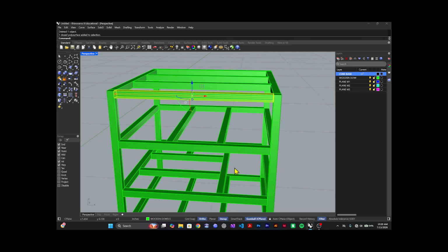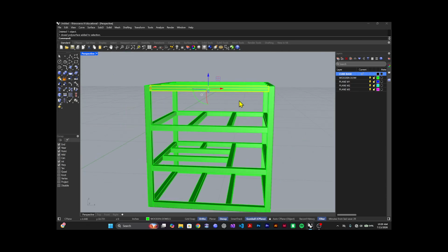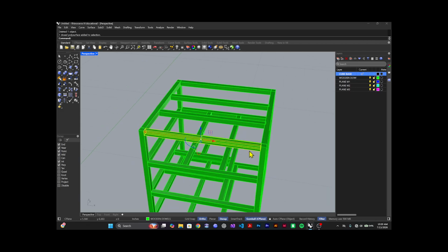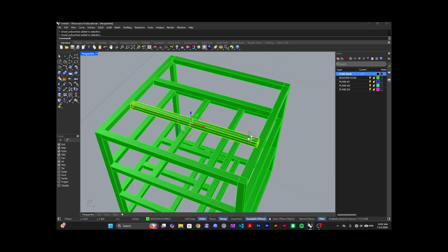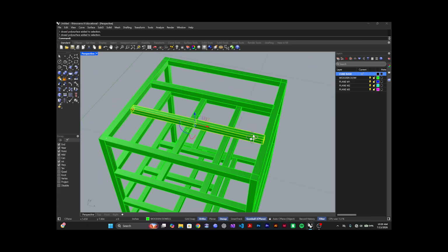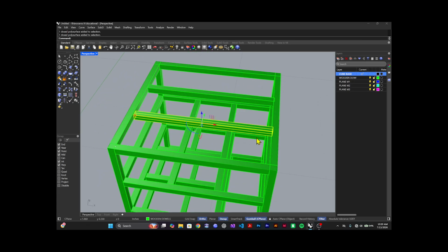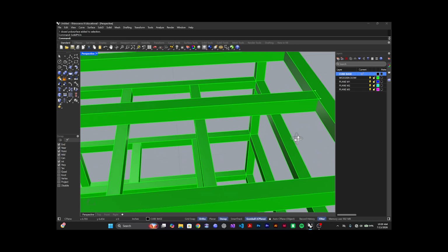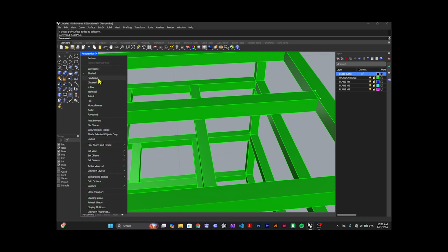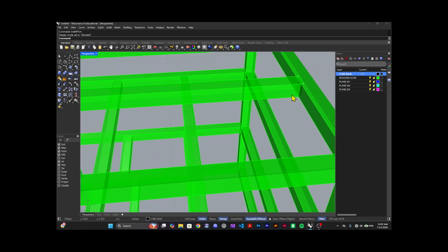You just select the one you want to edit or change, and then we type solid points on. Here it's kind of hard to see them, but if we go to ghosted, you're going to see the points right there.